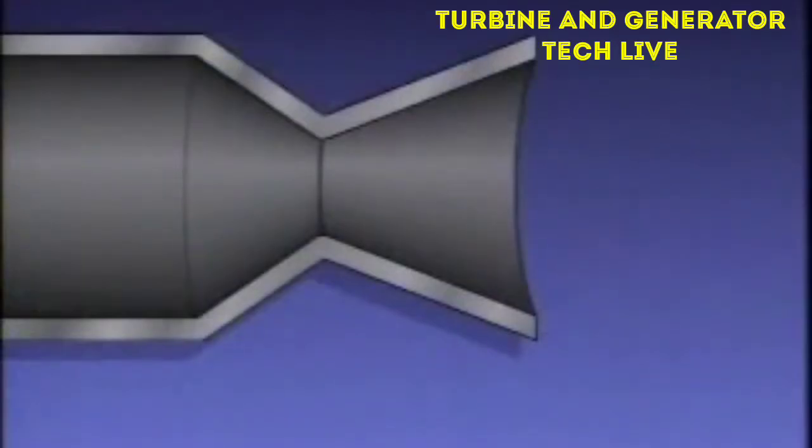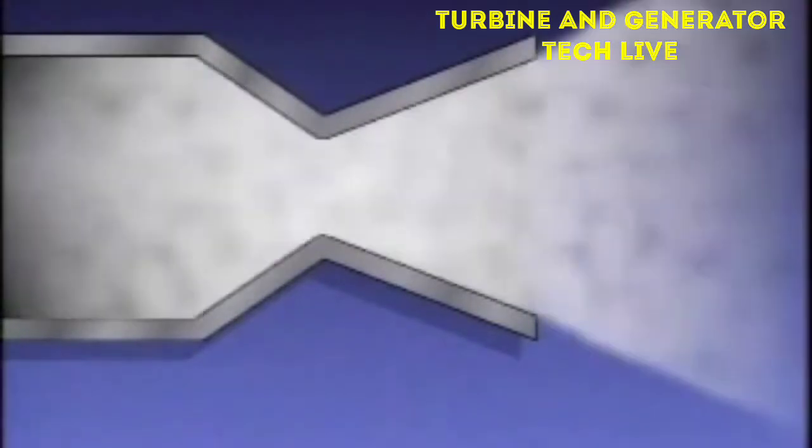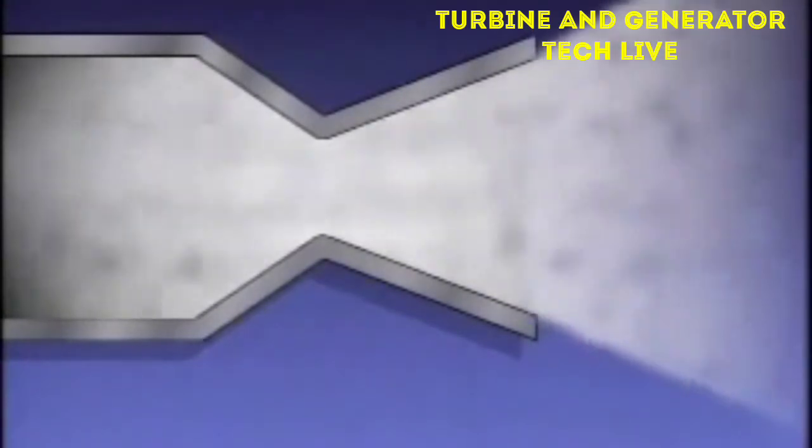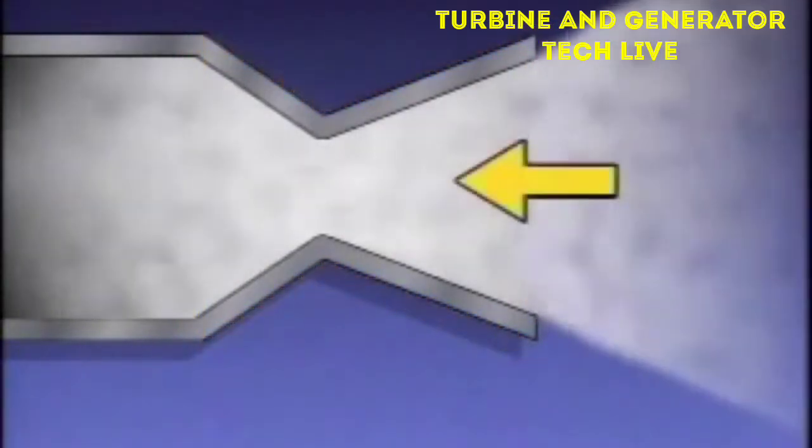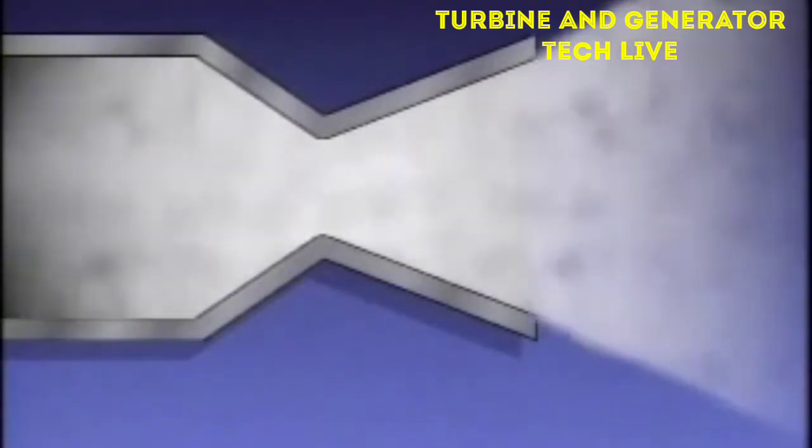This simplified illustration represents a nozzle that is part of a rocket engine. Hot gases from the combustion of fuel are exhausted through the nozzle as they leave the combustion chamber of the rocket. The nozzle causes the hot gases to accelerate to a high speed as they pass through the nozzle's narrow throat and then expand. The high speed creates a reaction force on the rocket engine that is in the direction opposite to the movement of the gases. This reaction force propels the rocket engine.